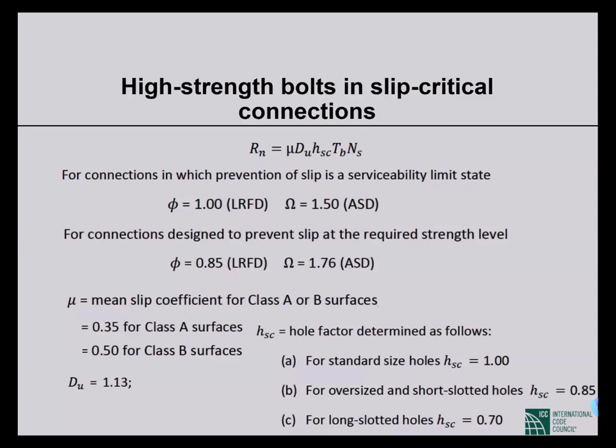Class A is the surface that is perfect, that is, if the surface is as fresh as it is just manufactured. So if we can prepare a surface, or just after manufacturing we put a slip joint, then the surface is class A. And class B surface is not like that, but still in the code there are provisions for what type of treatments should be there.